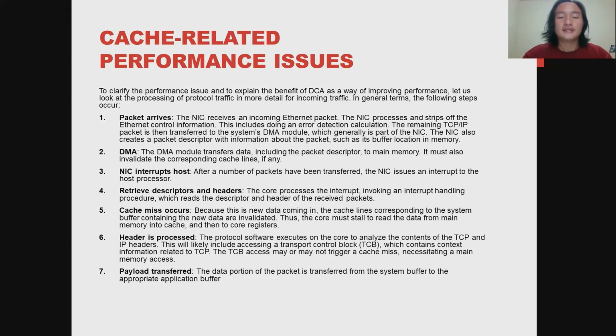After a number of packets have been transferred, the NIC issues an interrupt to the host processor. Retrieve descriptors and headers. The core processes the interrupt, invoking an interrupt handling procedure, which reads the descriptors and headers of the received packets.